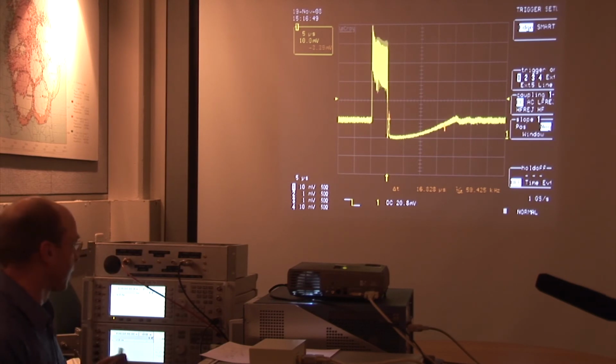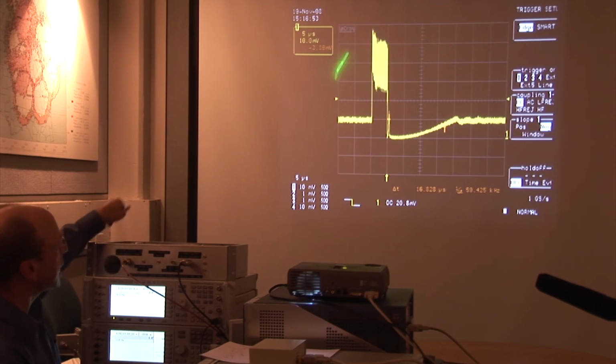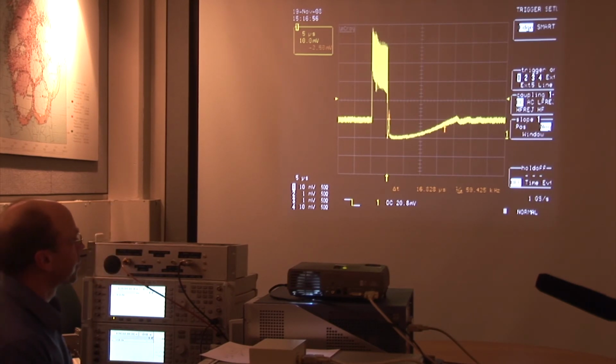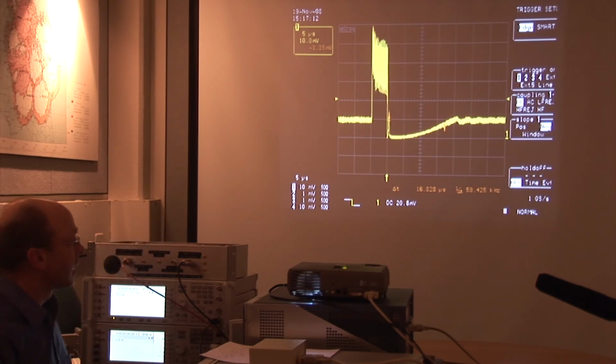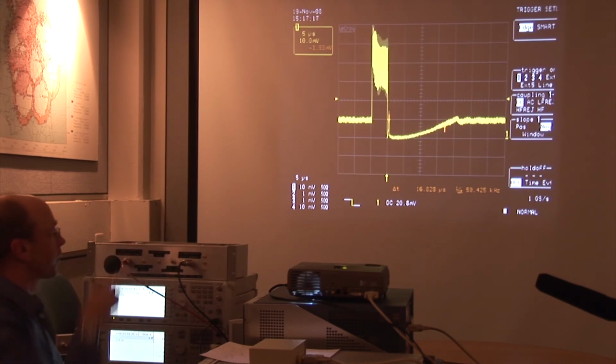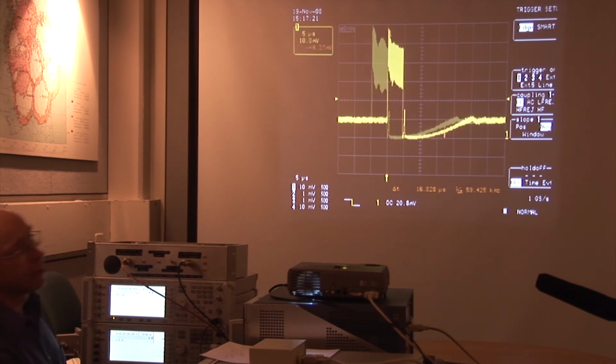So it's really as simple as that. And what we've demonstrated here is what you'll actually see on a spectrum analyzer and an oscilloscope with a detector. And we've also demonstrated that you can use either a spectrum analyzer or a scope combined with a detector if you want to diagnose this at a receiver site. Now, the other nice thing about doing this is you can do this, of course, without having identified any candidate interferer whatsoever. Again, if you see that happening, you know it's front-end overload. If you haven't identified a candidate interference source yet, you can go out and look for it.